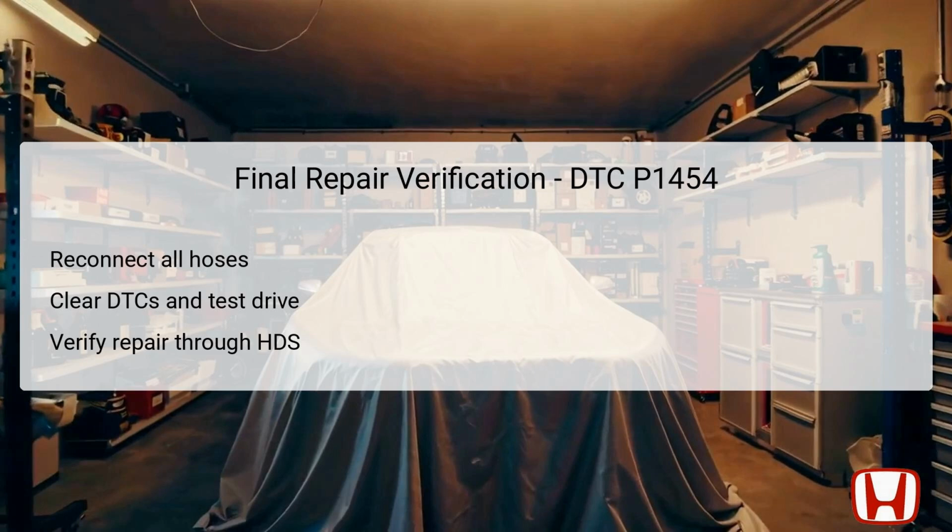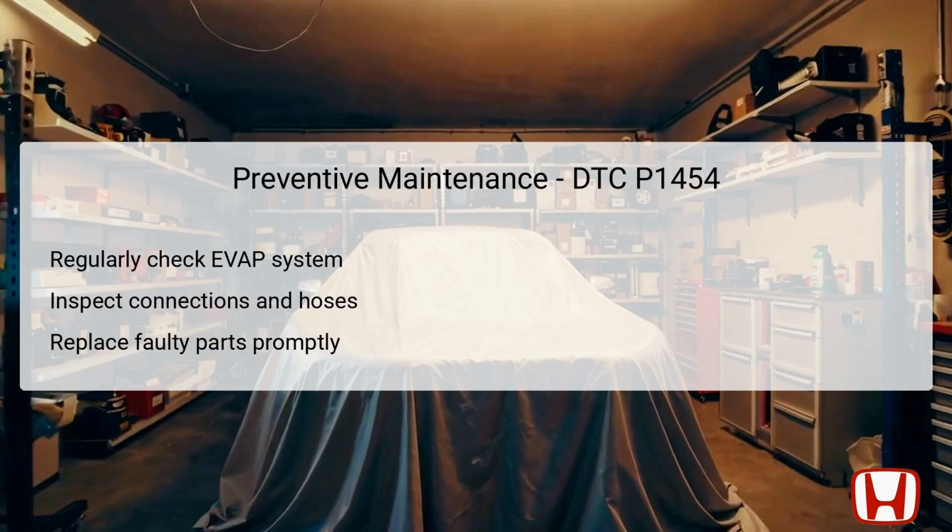Subsequently, the vehicle should be taken for a test drive under various operating conditions to gauge if the DTCs return. Monitoring the HDS during this drive is crucial to ensure that no new DTCs emerge, signaling underlying issues. Successful completion of this verification step assures that repairs are effective and that the vehicle complies with emissions regulations and operational standards. To maintain the integrity of the EVAP system and prevent the recurrence of DTC codes such as P1454,